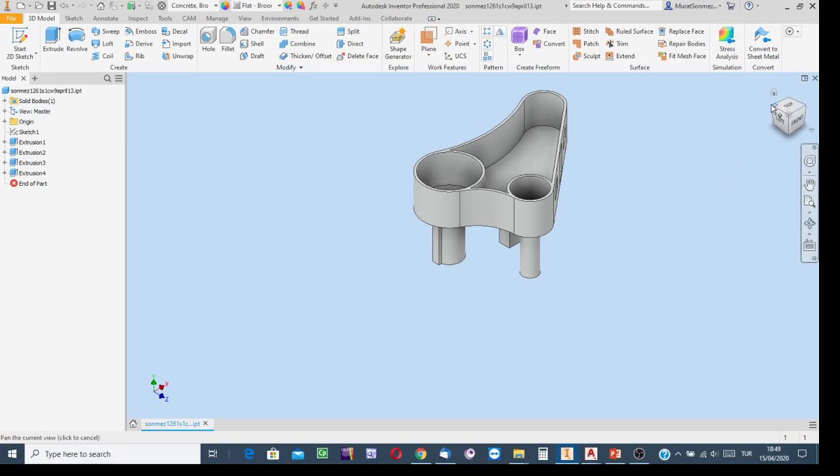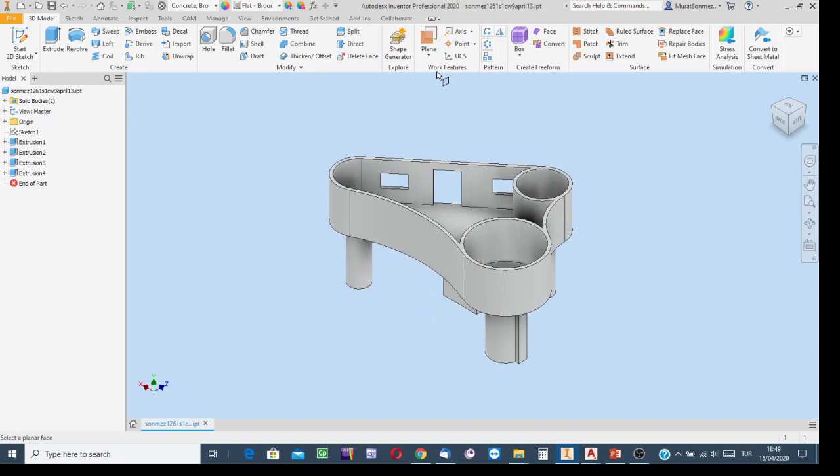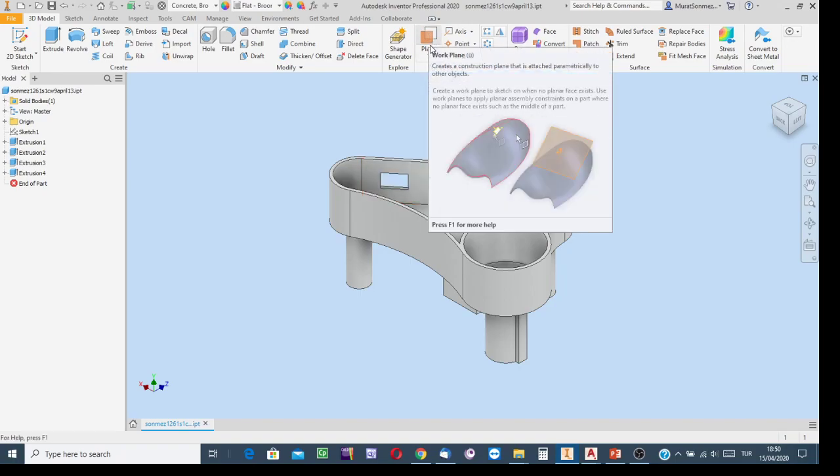If there were a flat surface, for instance here, I would start the work plane creation process and then say that this flat surface is the reference. Here at this site there is a flat surface to indicate. Okay? Actually, well, say oops and first focus your attention on this relatively easy case. For instance, you need to create a window opening and the direction of the opening is perpendicular to this flat surface. There is such a flat surface in the structure of the existing one. So there is no need to use a work plane actually. Why?